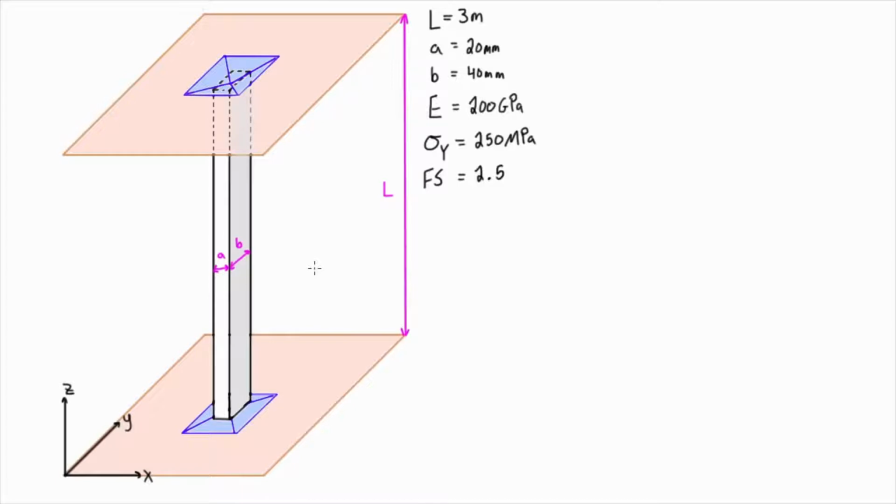So basically what we need to do is first figure out what our effective length is. Now considering both planes it can buckle in, it's considered to be pinned in both of those directions, so our effective length, no matter how we look at it, is going to be just the actual length of the column because it's that pin connection. Now that came from the previous videos where we were talking about different end connections, but in the next videos we'll do different examples. So for now, effective length is equal to the length where we have a pin-pin connection on this column.